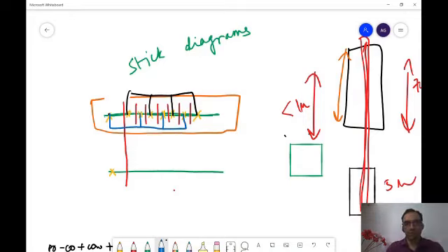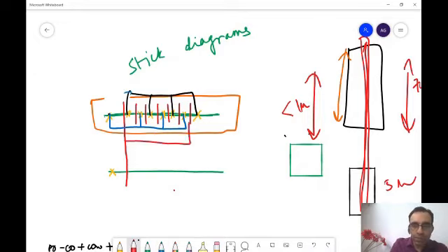So that black one is also metal, right? Black one is also metal. I'll just use VDD for black. And what else do I need to short? I need to also short the polys. Only then will the gate be connected.